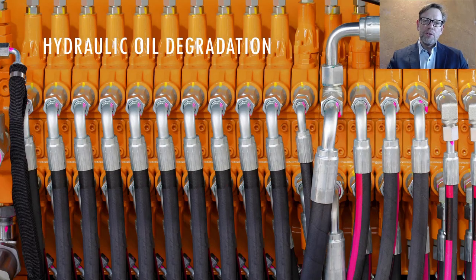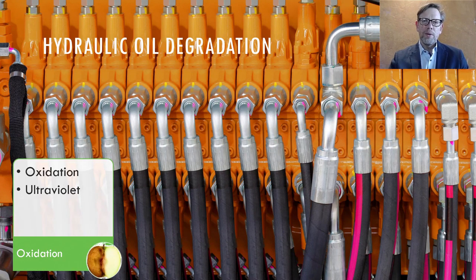So a few different mechanisms that we see in hydraulic oil degradation. By far the most common one that we deal with is oxidation. Virtually anything in the presence of oxygen has the ability to either donate or transfer an electron, causing the oxidative process to begin. Essentially, it's a formation of a free radical that will continue to react and react and react until something quenches that and neutralizes that free radical. That something is antioxidants, and it's why antioxidants are such an important ingredient in any lubricant that's used in an oxidatively stressful environment.